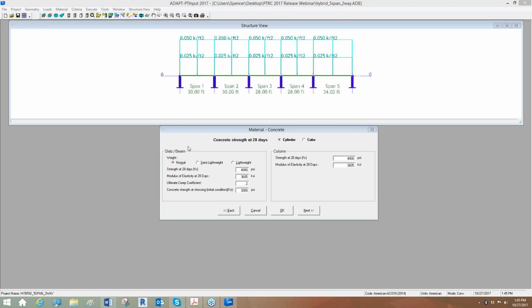One-way slab with transverse beams. Just wanted to confirm that we should switch off the transverse beam option because of the minimum reinforcement at the transverse beam, 0.004 for the top mild reinforcement. So yes, if you're doing a transverse beam design, you likely would not use the total area of the transverse beam for the minimum reinforcement over the support.